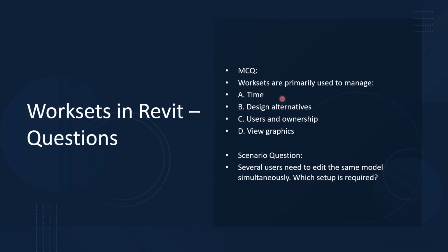Questions related to worksets. Worksets are primarily used to manage time. No. Talked about time. Design alternatives. No. Talked about this. Users and ownership. Yes, this is the solution. If you want to manage users and ownership of the elements, the design, manage the responsibilities and tasks, worksets is a very powerful tool.